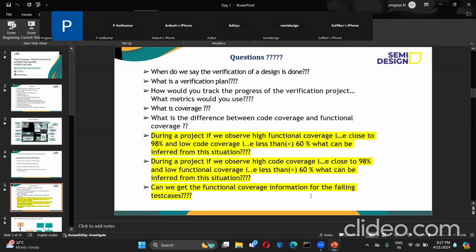One of the main metrics is coverage. One thing is that the test cases should be passing. We will be doing the regression suite. Regression means all the test cases will be running in one suite, running in parallel, with different counts so that randomization occurs and different seed values get exercised. Through that, we will capture our coverage, and we will also see the number of test cases failed.